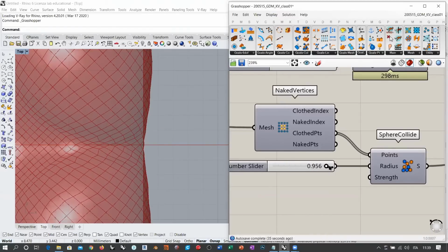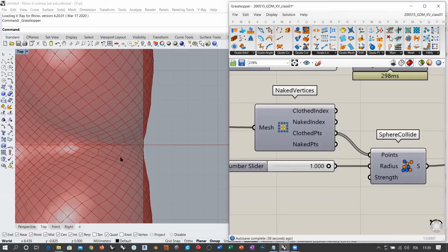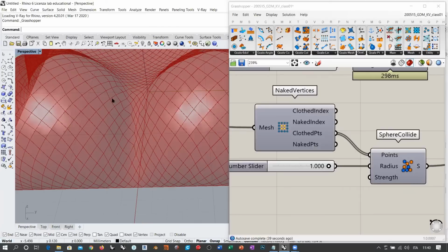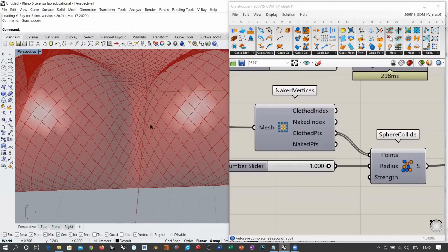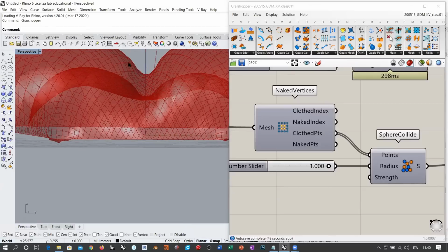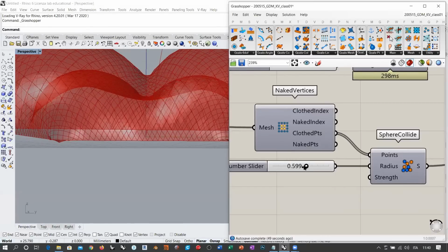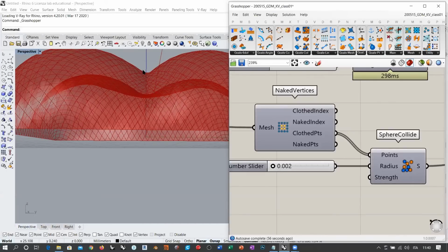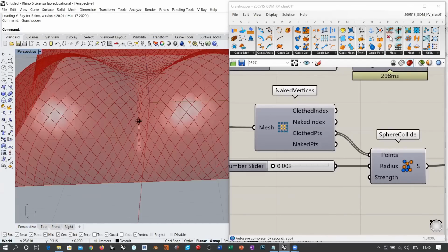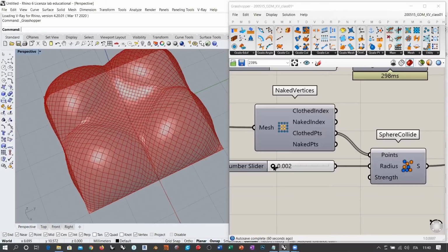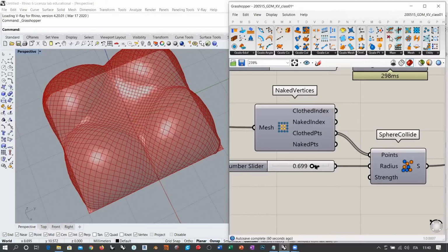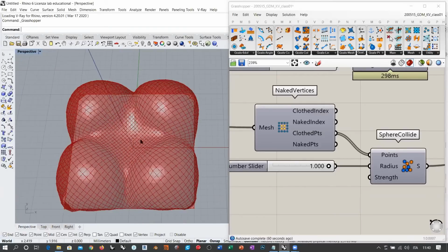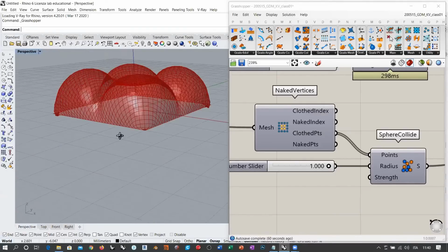Actually, it is not inflating more. The vertices are separating from each other. Now, this is good for this particular portion of my mesh. You see that this is stretching and smoothing, okay, the aspect of the mesh. If I decrease this, I am back to the original situation where my vertices in this area tend to overlap more, okay? So this is a control that allows the mesh to be kept separated, okay? So this tends to avoid self-intersections, okay?